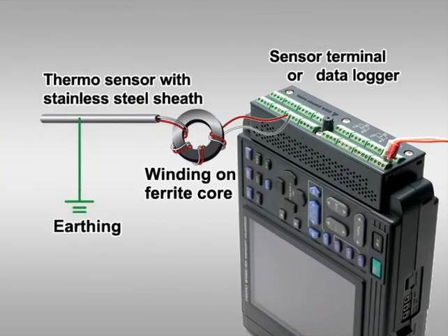Installing an electric product that contains power converters, an inverter for example, near a normally functioning temperature measuring instrument could result in erroneous display of error or overrange warnings. One possible reason for this is noise generated by the power converter entering the thermocouple. This noise is known as common mode noise. Temperature measurement can be improved by taking the following actions.